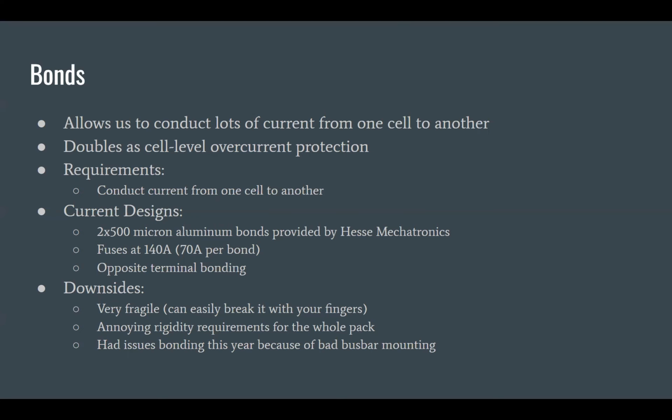One of the other things we'll see more in the bus bar parts is that because we used a water jet and adhesive to make our bus bars, a lot of our bus bars were bowed, which meant that they could wobble up and down in the middle. They had weird gunk on the surface, so they didn't make good contact with the metal. And the adhesive on one of the packs actually ripped off. One of the bus bars just